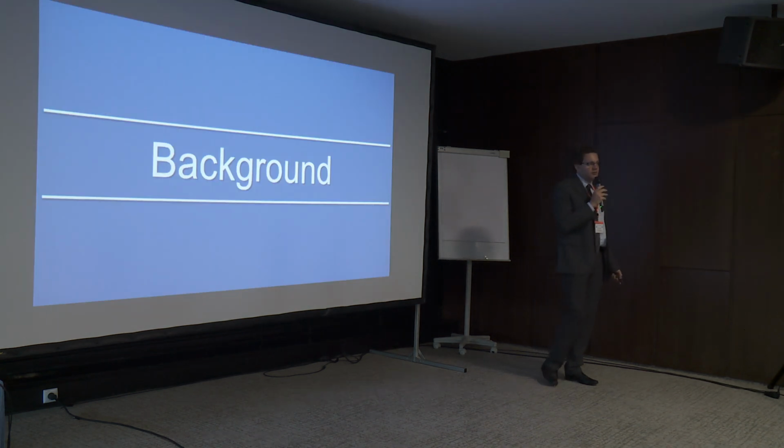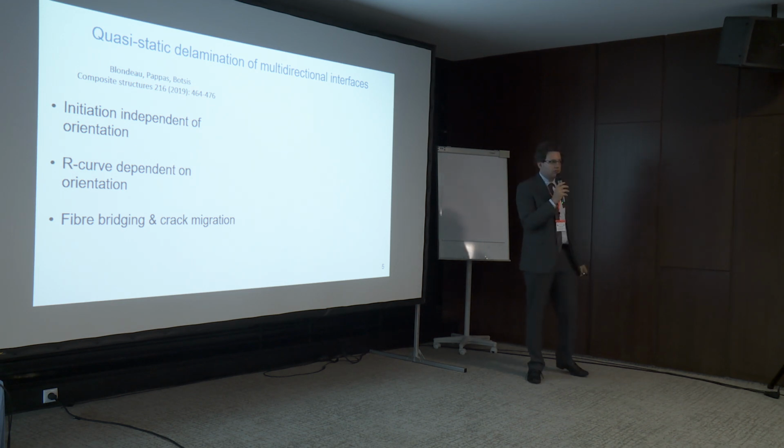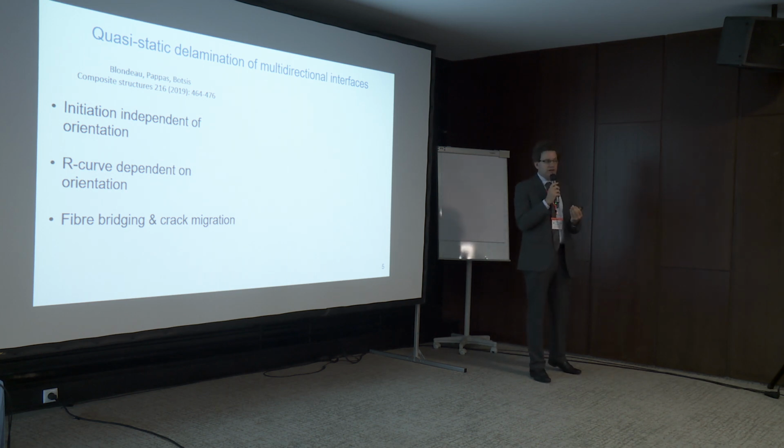Well, there's some background that we could already rely on from the literature, because the quasi-static case has already seen quite some study. There's a nice summary of that in the introduction to the paper by Blondeau and co-workers that I quote there. The short version is that the initiation fracture toughness, the quasi-static initiation, is independent of the fiber orientation, whereas the propagation fracture toughness, the R-curve behavior, does depend on the layup.